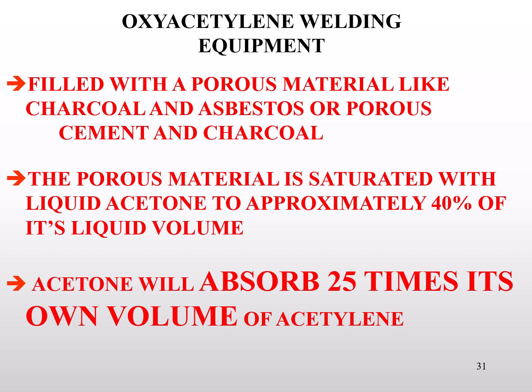Unlike oxygen bottles, which are hollow, acetylene bottles are actually filled with a porous material similar to a very lightweight, porous concrete or cement. Now, also, they are filled to about 40% of their volume, not quite half, with liquid acetone. Acetone is typically a solvent and a cleaner, but in this case, it serves a much more important role.